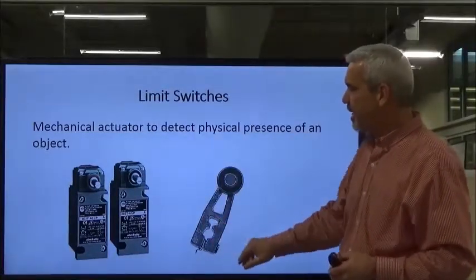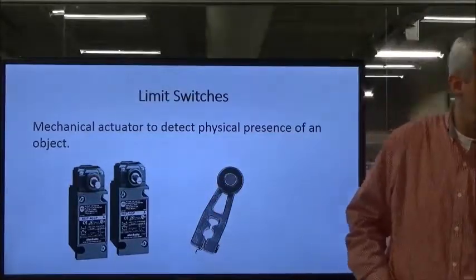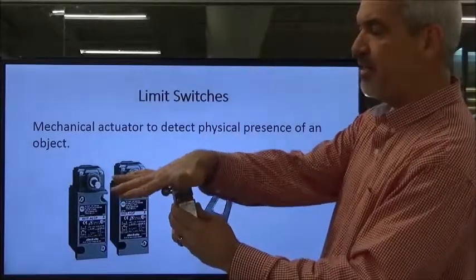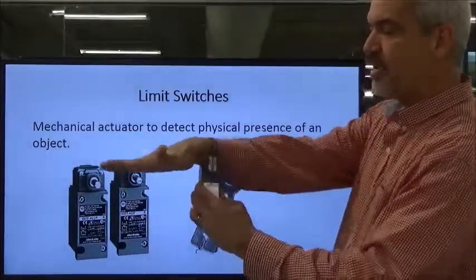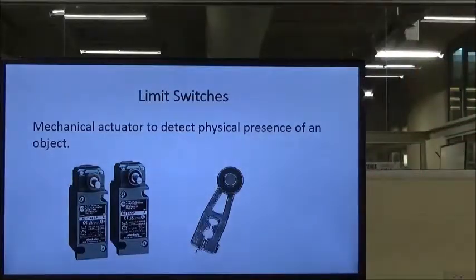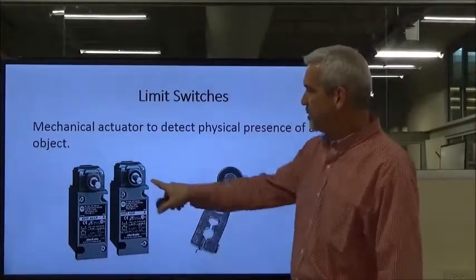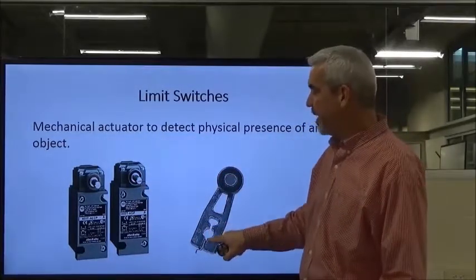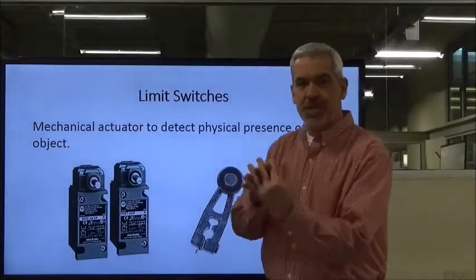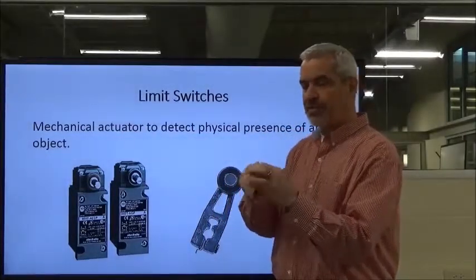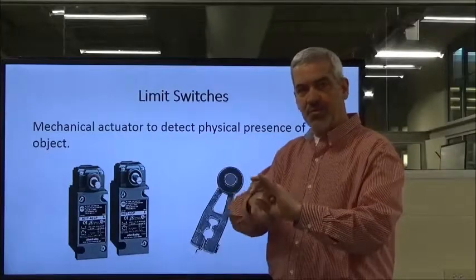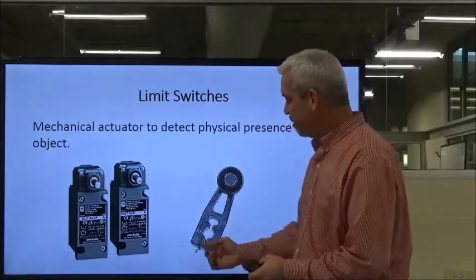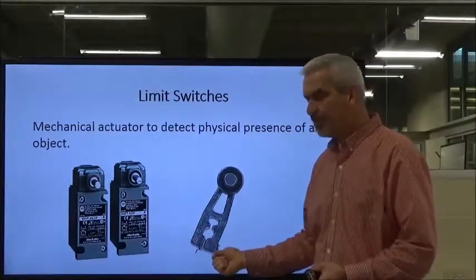And again, you have different types of actuators. This is the roller type. It's got a little roller, okay? It just lets it roll right across my finger like that, and it makes that switch all day long. And this tightens up against the shaft here. The shaft is usually splined, and so is the receiving hole in the actuator, so that you can get a good tight grip, because after a lot of cycles, it would want to slip if it was just a smooth finish. But they have splines to grip tight, and then you tighten up the clamp, the gripping pressure, right there with that screw.